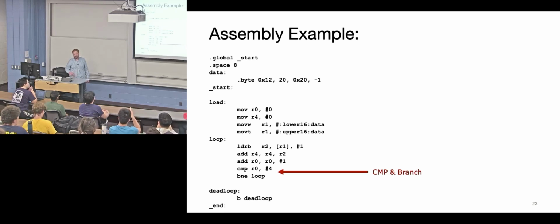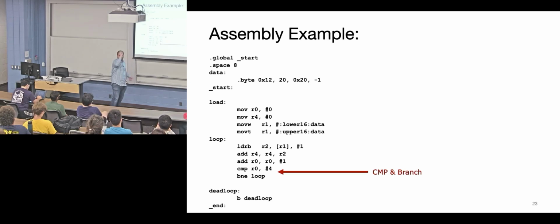What's called the least significant bit or least significant byte, right? Correct. It'll do this one first. This is byte-wise, not word-wise. So it's going to put the first byte in, then increment the address, second byte, like that. If I had a second byte command, would it append to the previous byte command?